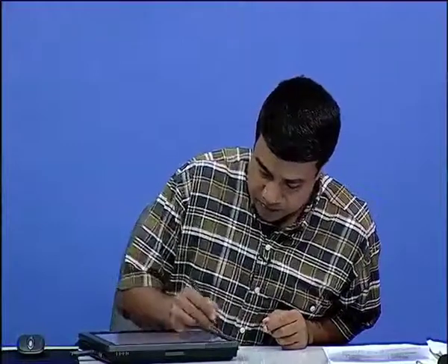Here the shear stress is written as the turbulent viscosity times the strain rate. So you write the shear stress tau ij is equal to, of course, there is the molecular viscosity plus there is a turbulent viscosity times grad u, in indicial notation, partial u i by partial x j plus partial u j by partial x i.